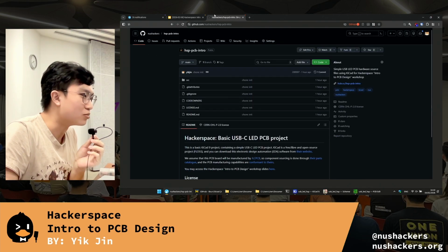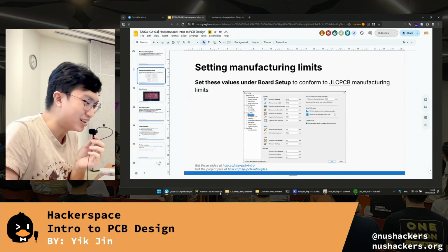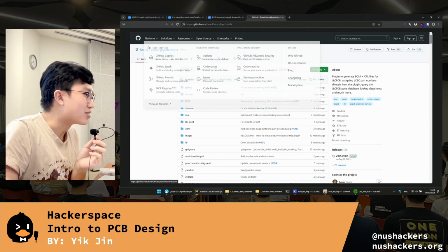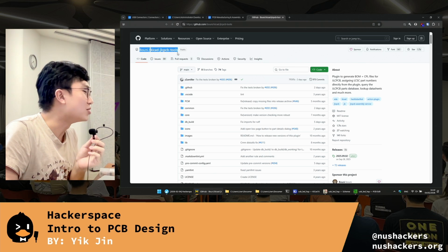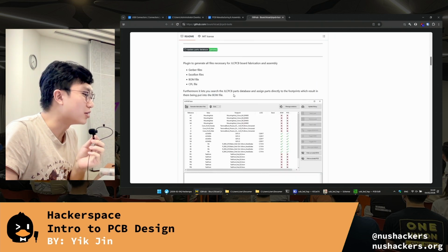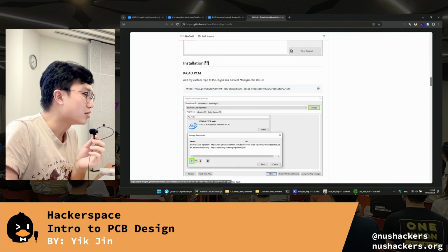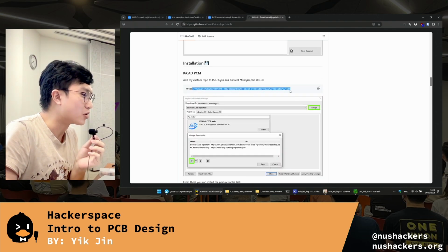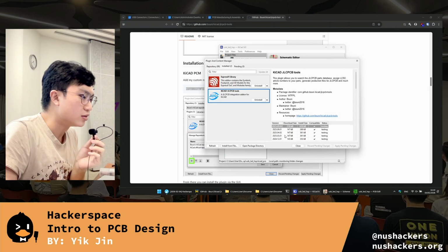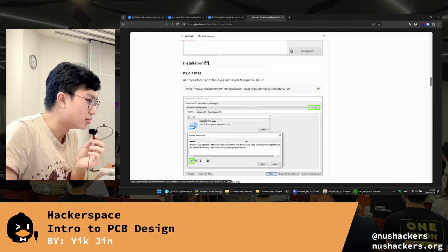I didn't put the link here. Okay. Yeah, if you search for KiCad JLC PCB tools, it should come up. Then you go down to the installation instructions. You can just follow the installation instructions here. So you copy this string into the open package directory.